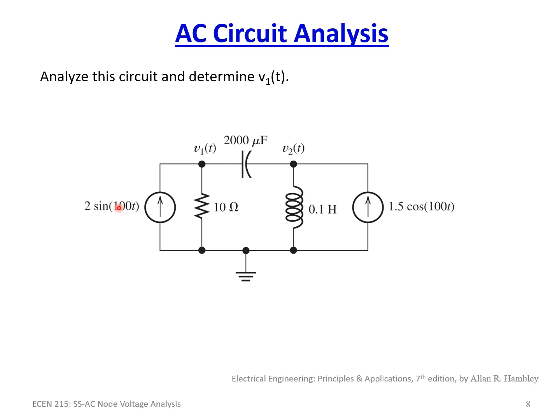So if I gave you a frequency of this circuit of, say, close to 16 hertz, 15.9 hertz, and then asked what is omega, you would do 2 times pi times that, and you would get approximately 100. If it was 16 hertz, it'd be a little over 100. For 15.91 hertz, you would get 100 radians per second. So that's our first step.